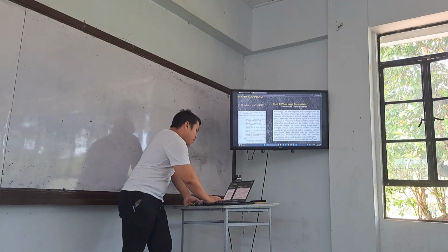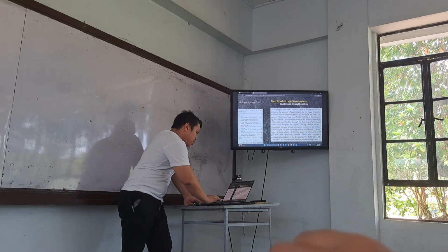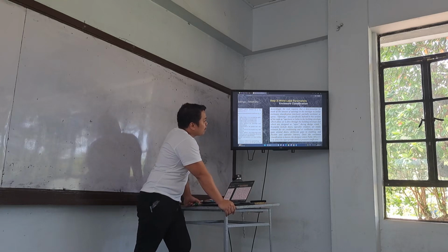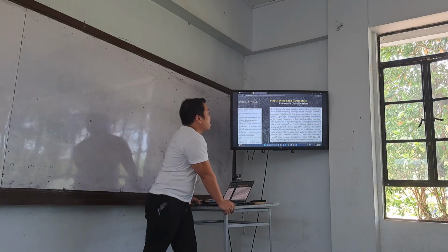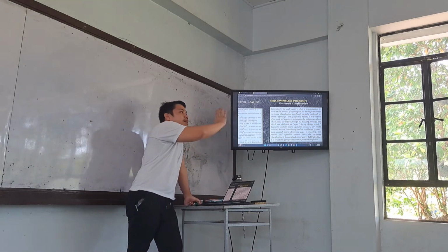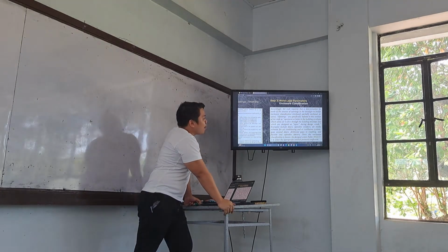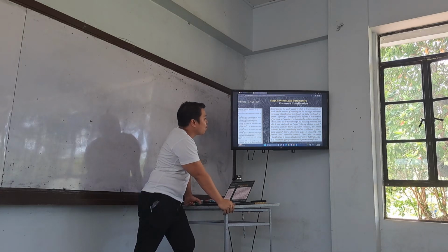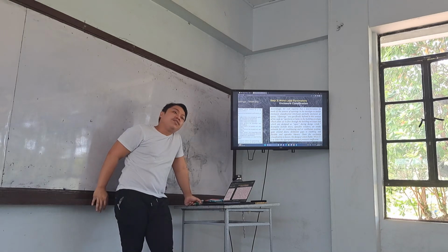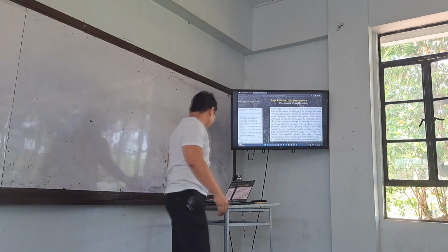And as per commentary, when we refer to openings, openings are specifically defined in this version of the code as apertures or holes in the building envelope. Meaning, every part of your building envelope that has an opening, which allows air to flow through the building envelope and which are designed as open during design winds. So what do we mean by that statement?